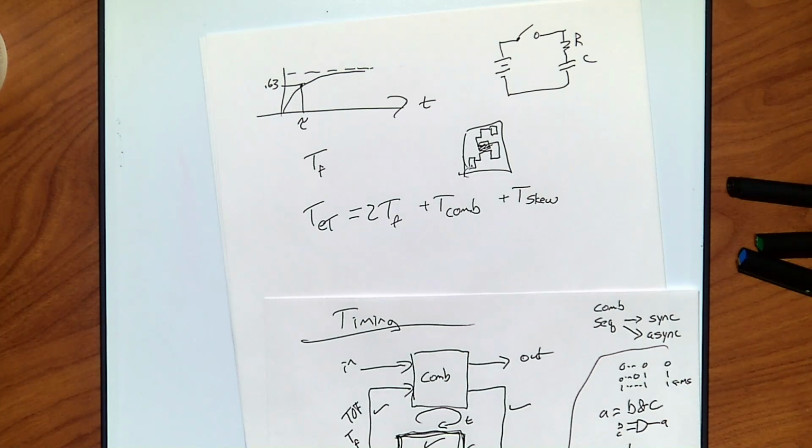That allows me to prevent skew, so I can time precisely. If you're going through the logic layer, my clock would follow some stupid route that's really tough to calculate. So we just disallow that. FPGAs will never allow you to clock off of a logic signal. And if you force it to, it's going to build separate logic that you can't send the clock through.